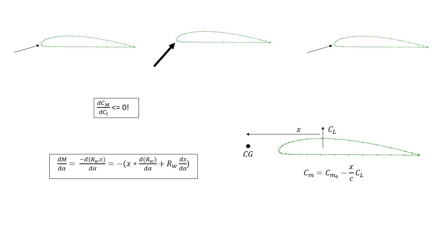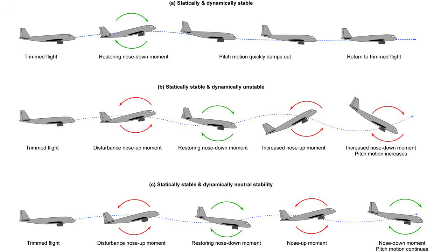And you might think, if we need the pitching coefficient of a plane negative, why not go all in and make it extremely negative and extremely stable? Well, as the pitching moment coefficient, if less than 0, can be thought of as the pitching stiffness, becomes increasingly negative, the aircraft will become more and more difficult to maneuver from steady flight. And if an aircraft is too stable, it'll be sluggish and difficult to handle. Again, this was covered in part 1, so see that video for a bit more of an in-depth discussion and derivation on this.